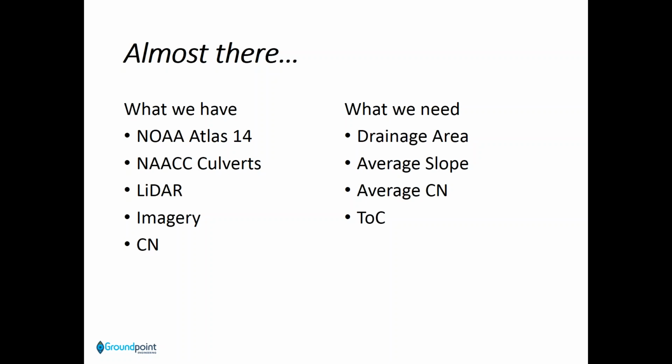But what we really need is what? Drainage area, average slope, average curve number, and time of concentration for any point on the map. And that's where the LiDAR data comes in. And didn't we say at the beginning that this is really a story about LiDAR?